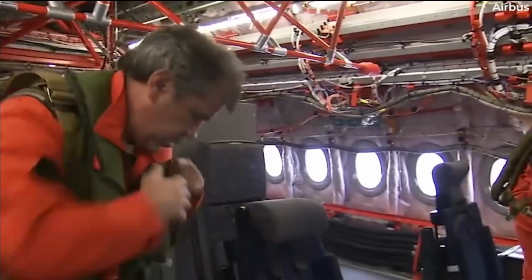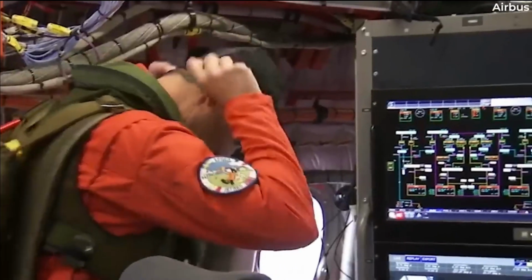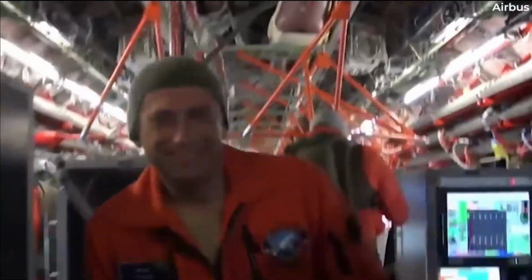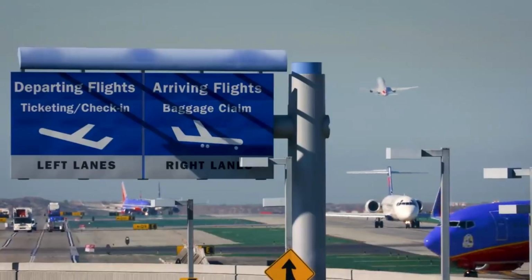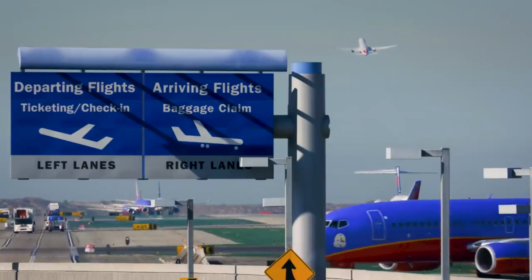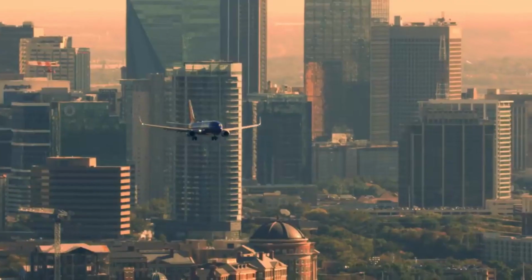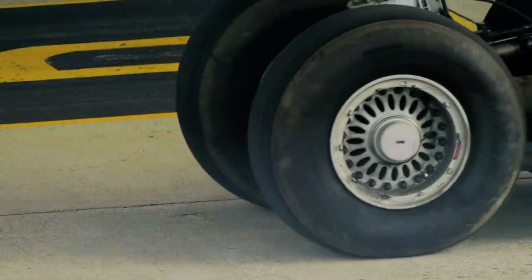Conversely, sometimes during maintenance, especially STC modification, the STC is addressed later in this chapter, it becomes necessary to temporarily place the aircraft into Special Airworthiness Experimental. This is done to show compliance with federal regulations. These aircraft must still be maintained in accordance with 14 CFR Part 43, because the aircraft had a different kind of airworthiness, in this example a standard, prior to being issued the Special Airworthiness Certificate.